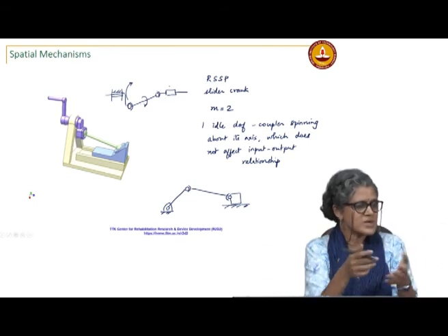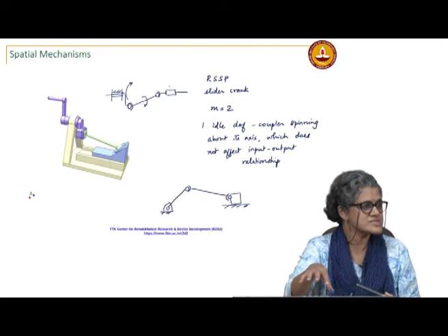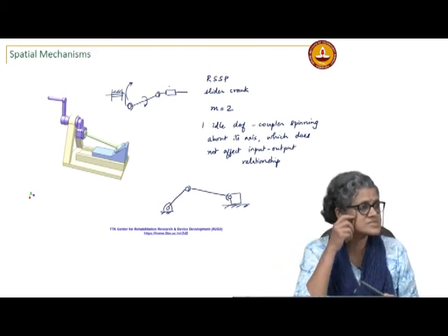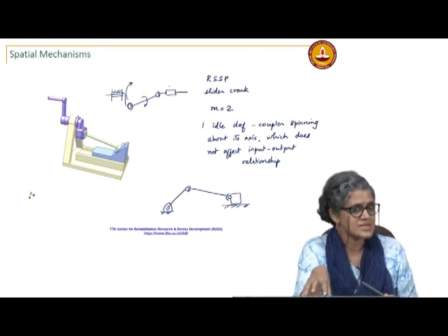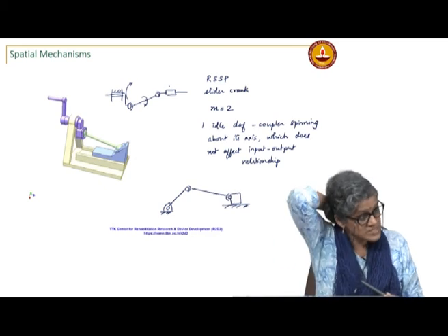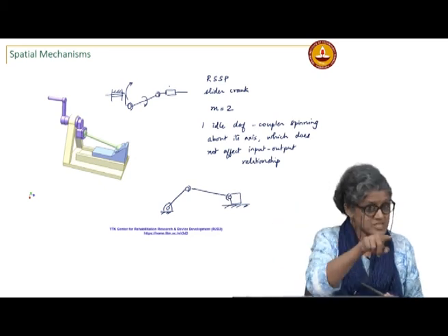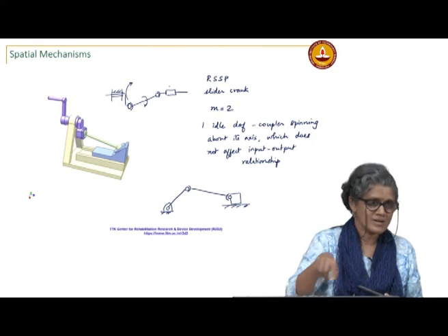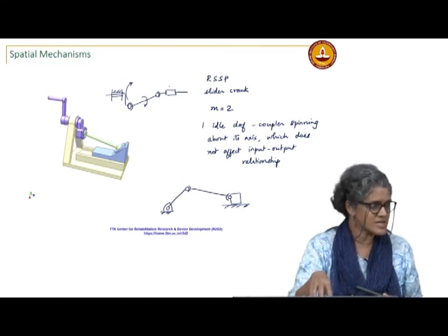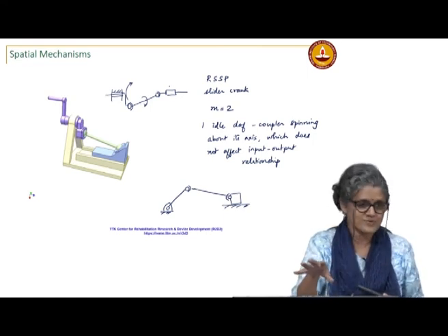So his question was, if it does not move, does the mobility equation still apply for this case? Why is it not showing mobility equal to 0? Again, special geometry, right? It is not a structure where nothing moves.